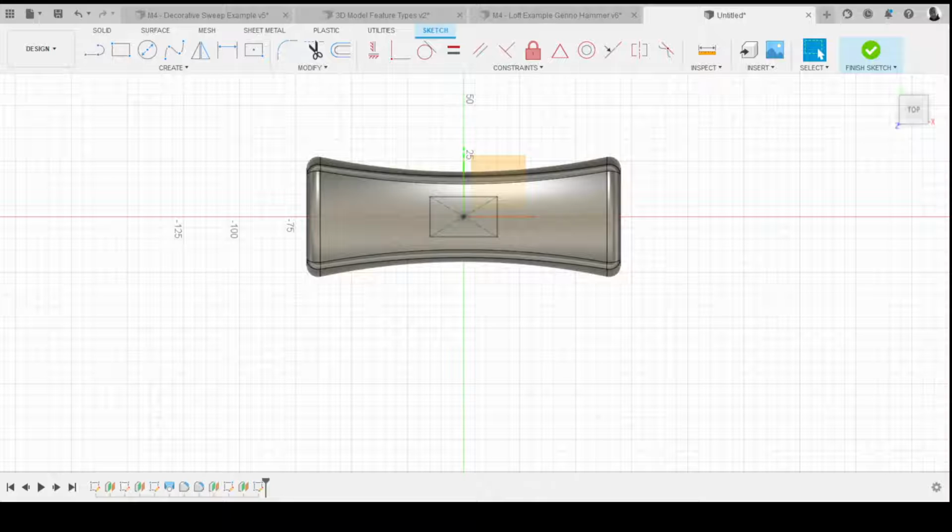And it's a bit like what we've just done. What might be the best way of making a slightly bigger version of this rectangle? Project it. Can we go straight to offset? No, we can't. It would be nice to go straight to offset, but we're going to have to project it first and then offset it. So in this case, I'm going to have to select all 4 lines to project. Project it. You can see it turns purple. And then offset, which is O on the keyboard.